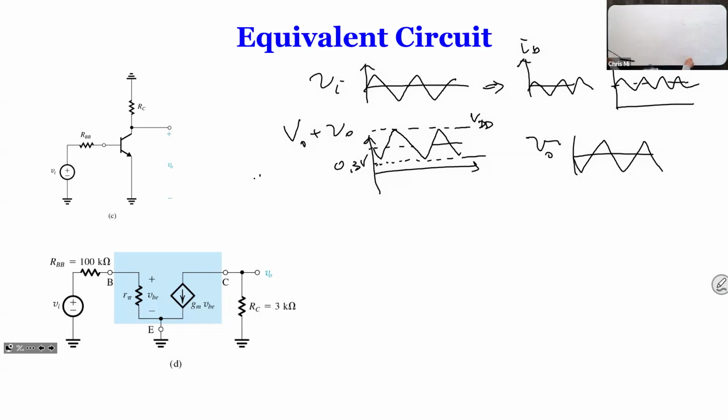You need to make it smaller. Well, one of the things you could do, for example, is add a resistance over here so that your input is not as big, right? That's one thing. Another thing you can look at is your GM: reduce the GM. When you reduce the GM, it means your IC and things like that have to change, right? Your GM is related.